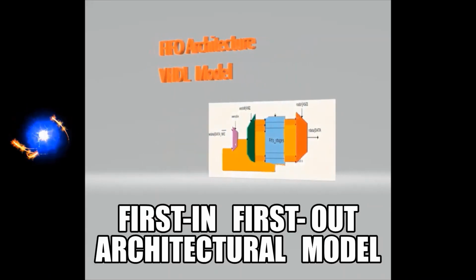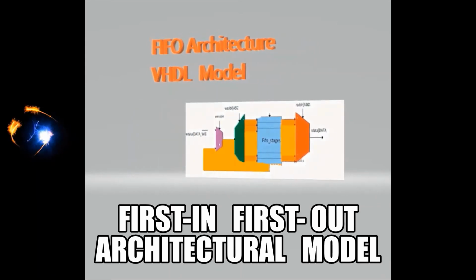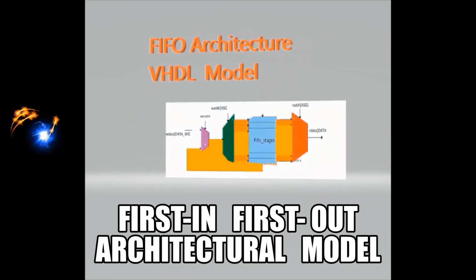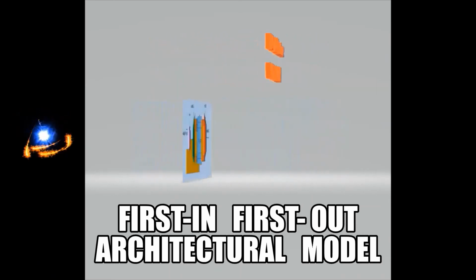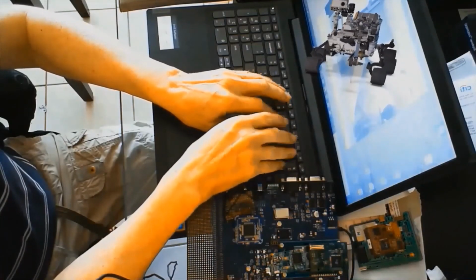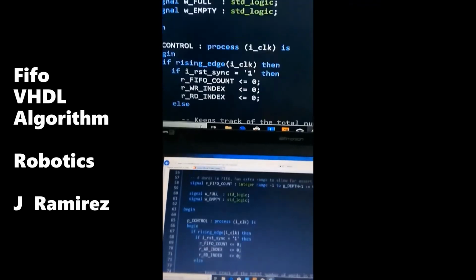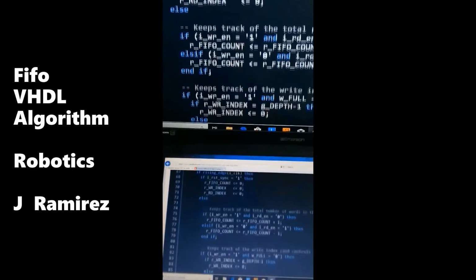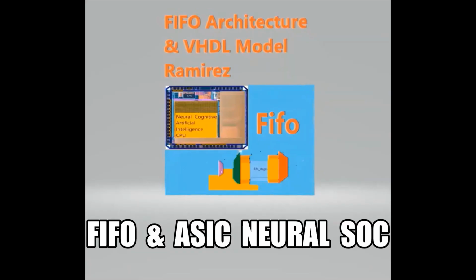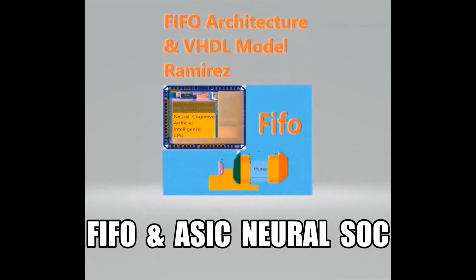In order to write data into the FIFO, first in, first out, first push the data onto the data in bus and then strobe the write enable input high for 1 clock cycle. It will write whatever is on the data in bus into the FIFO's internal memory. For writing in bulk, the write enable signal is left high while changing the data on the data in bus each clock cycle.